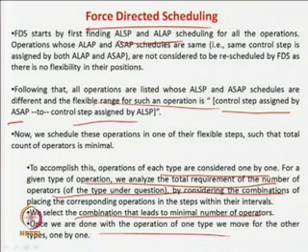So what it basically says is that we first take multipliers and try to make a schedule such that the minimum number of multipliers are required. Once the multipliers are done, then we go for adders and so forth. But this will not always lead to an optimal solution, because when we schedule some multiplication operations, based on data dependency, the flexibility of the adders or the subtraction operations may also change.